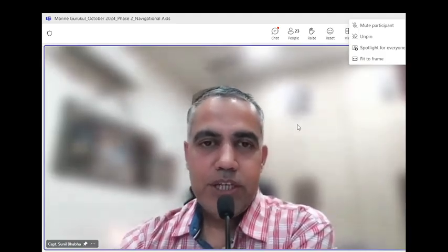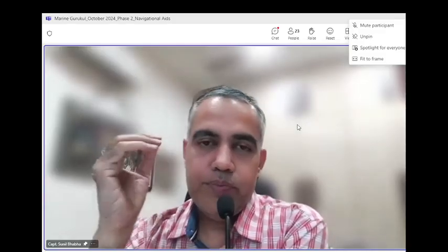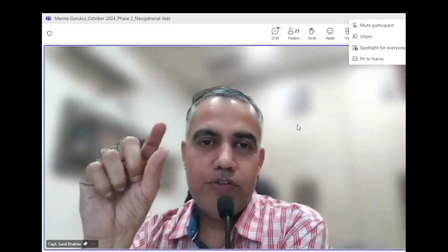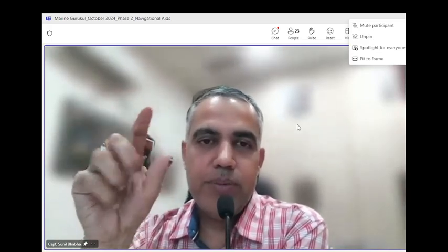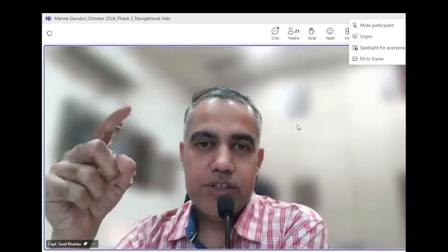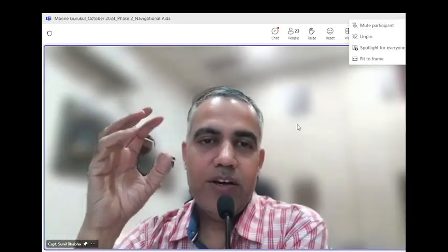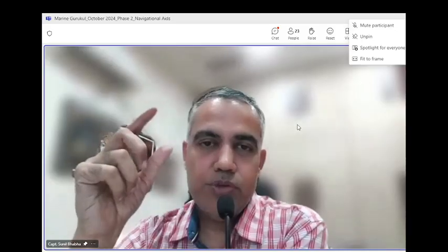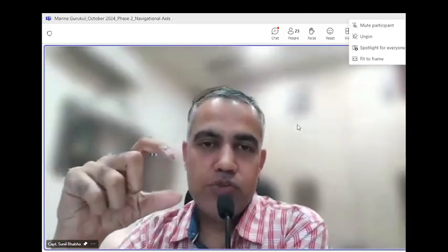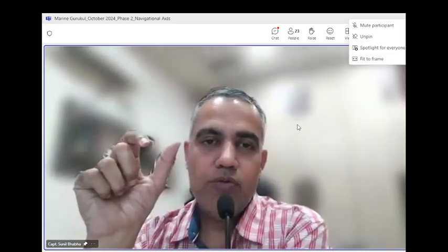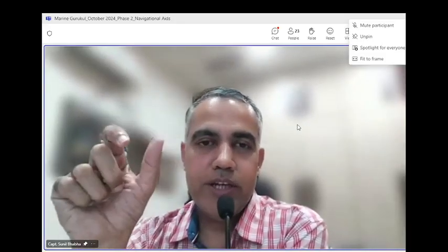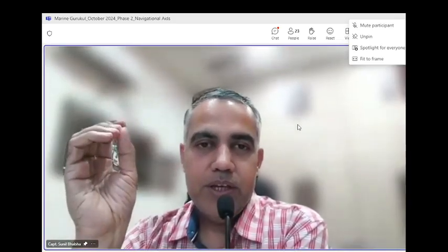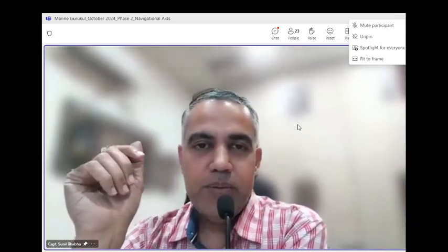So we will be proceeding today into further topics. In the video, you have seen that the rate of turn of the ship in a particular turn is given by V upon R. V is the speed of the ship and R is the radius of the turn. So once you know the speed of the ship and the radius which you have planned, you can calculate the rate of turn which is required by a ship to execute that turn. So this is the basis of turn planning.